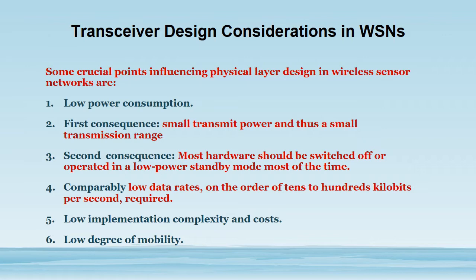In that situation, if the node is continuously activated for the entire 24 hours, it will drain the entire energy. So that's why, while designing the transceiver, we have to activate the node whenever the event is occurring. The remaining time, the node will be in sleep mode.